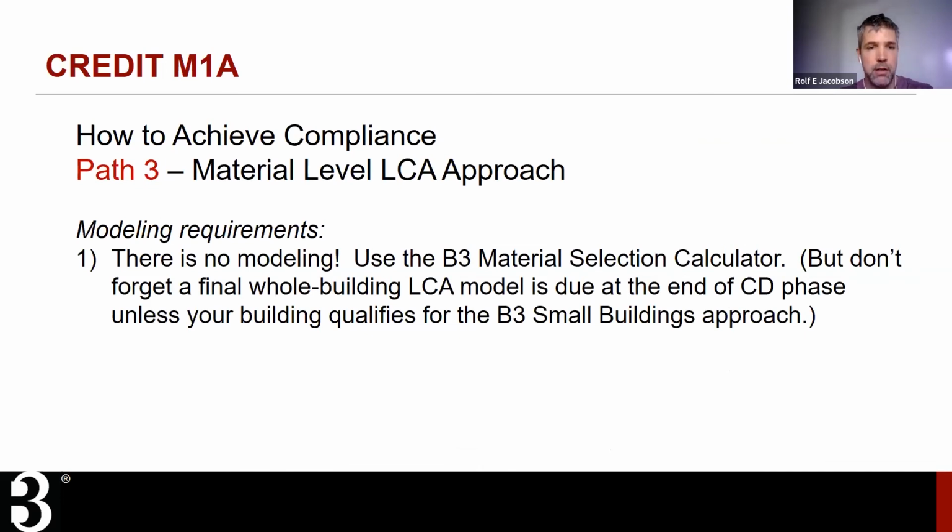Okay, modeling, again, there are no modeling requirements. We're using this selection calculator. However, it's important to keep in mind that if you do select this approach, one whole building LCA model is still due at the end of the CD phase, unless your building is fitting under the B3 small buildings approach, then that requirement is omitted.